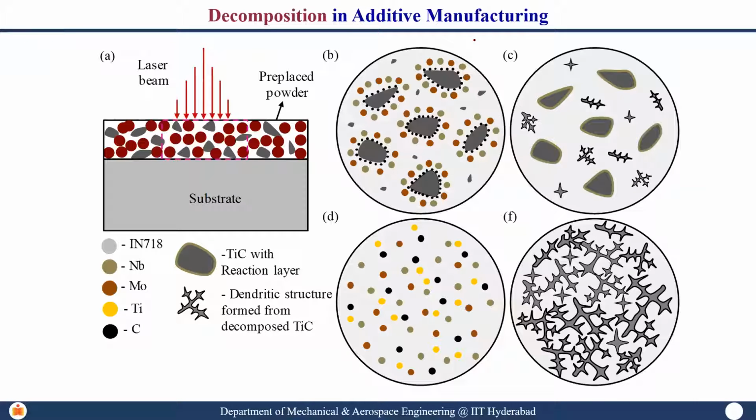So here, you have Inconel plus 30% titanium carbide. You will get the desired property as long as titanium carbide is in its original form, I mean, you have taken randomly shaped particles. This is the IN718 matrix. There should be good wetting between the matrix and the particle. But remember, this should not get dissolved or dissociated and convert into dendrites like this.